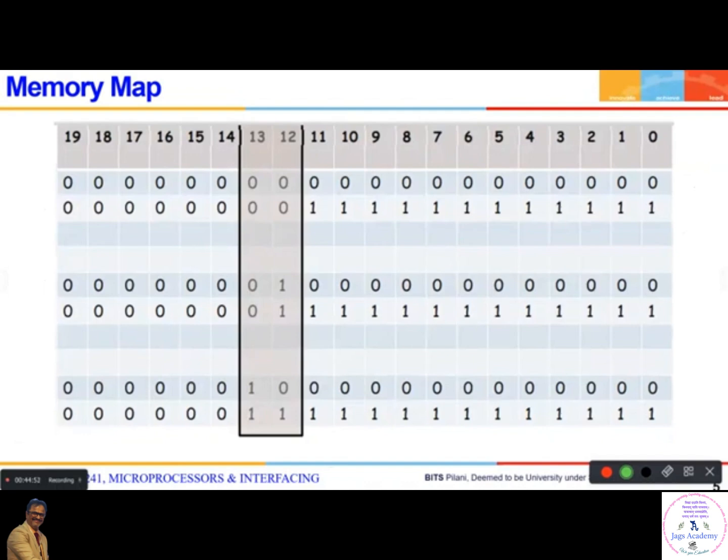This table is very important. Have you understood reaching this table, at least as of today? After this table, you have to think and spend some time. Out of these address lines, which lines go to the address lines of the chip, which line selects even and odd, which lines are given as select inputs to the decoder, and which lines are given as enable inputs to the decoder.